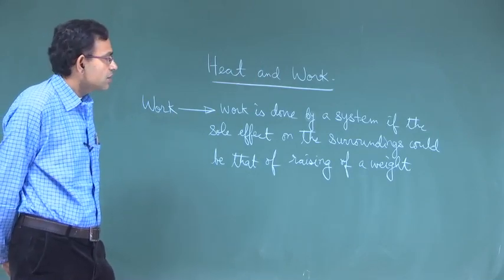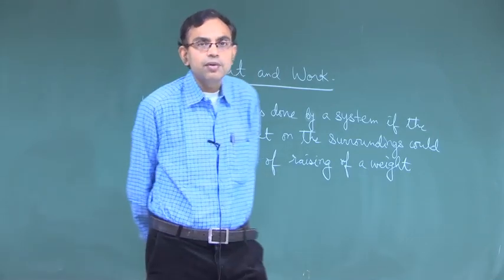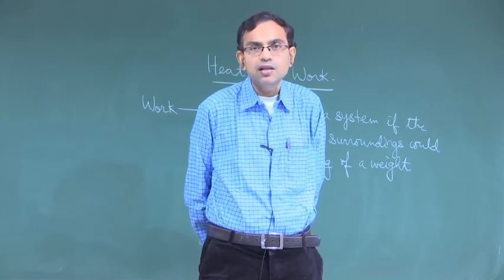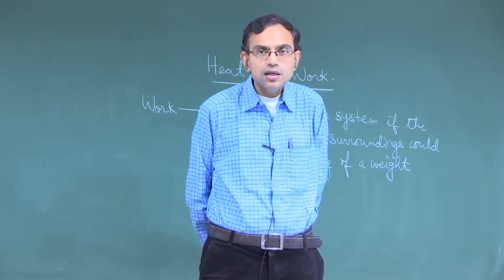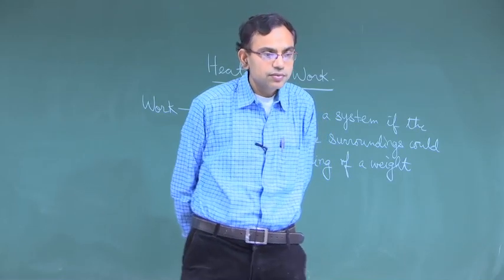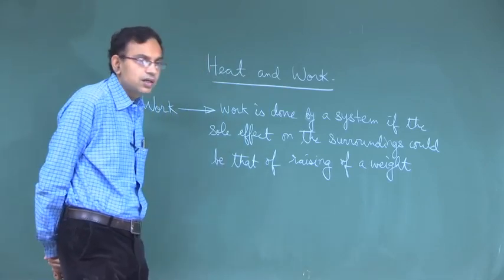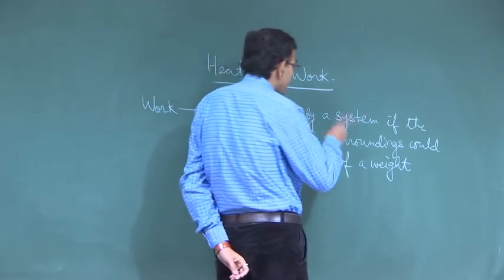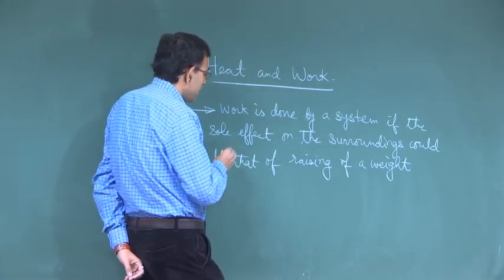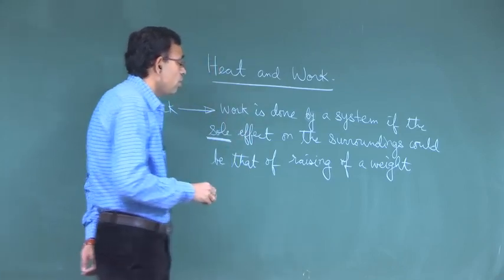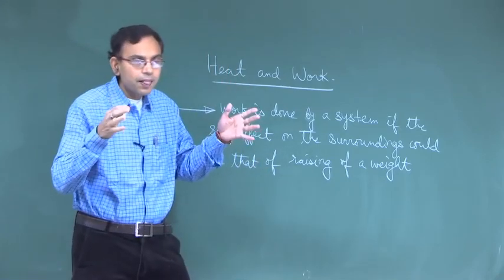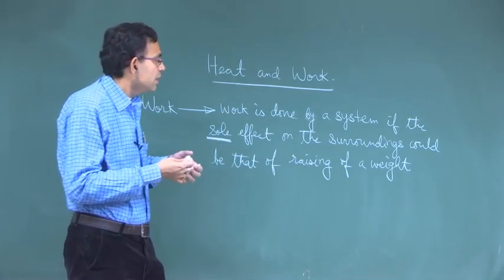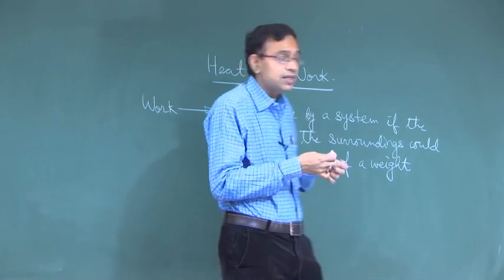Okay. So, this is a very tricky statement. The statements and definitions in thermodynamics are pretty generic, sometimes very philosophical, so it is very important to interpret between the lines. So, work is done if the sole effect on the surroundings... So, there is a system and there is a surrounding. The system is doing some work if the sole effect could be that of raising of a weight.